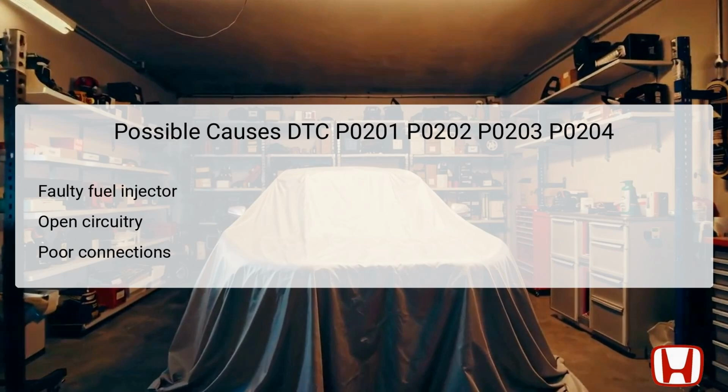Several factors can lead to the DTCs being triggered. First, a faulty fuel injector itself could be the primary culprit. Injectors can fail internally, affecting their resistance and functionality. Second, open circuitry is a common issue where wires may become disconnected or break, interrupting the electrical flow needed for